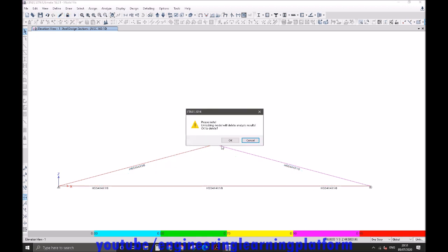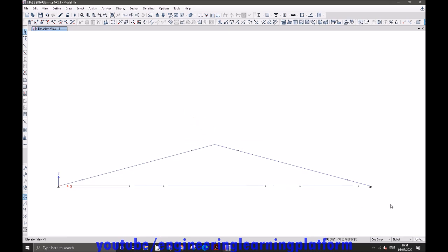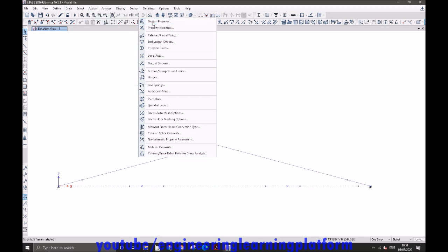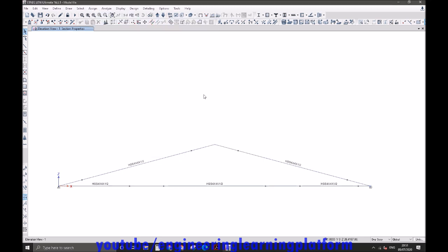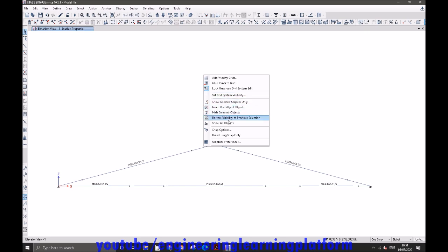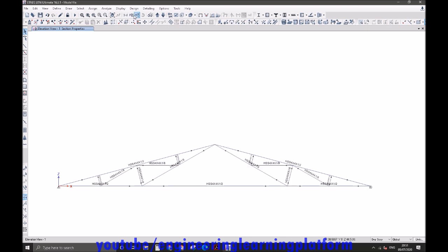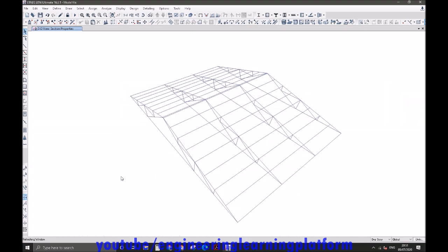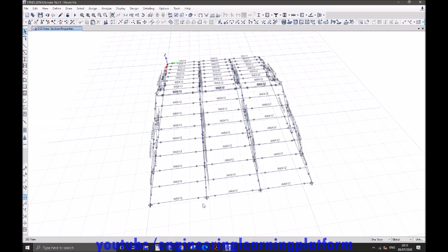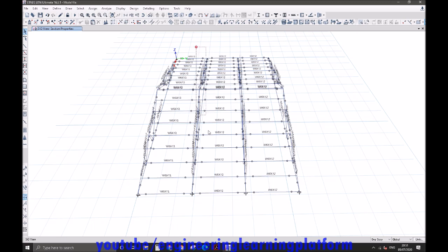And assign the largest passing member for the top and bottom chord. Usually these members are similar, as they are the primary frame of the truss, or the primary members for the exterior perimeter of the truss. From detailing and site execution perspective, it should be easy to execute. I'll have to delete the rest of the trusses and replicate that for a fast track approach.